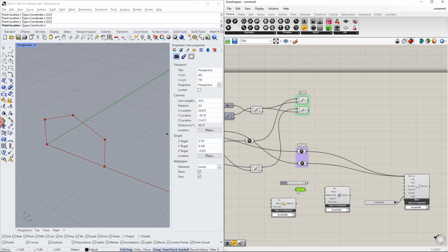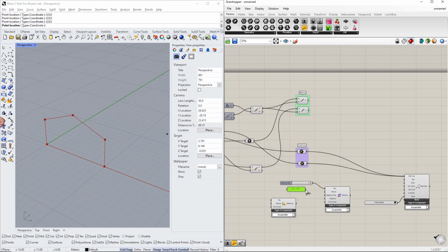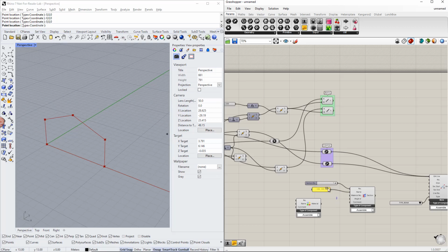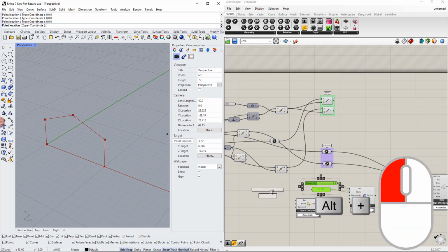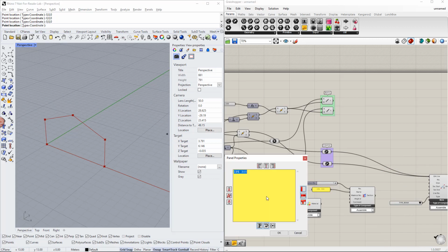Now we enter these properties. For the cross-section, we enter 1 as the section number and IPE 300 as the cross-section name. For the material, we enter 1 as the material number and S235 as the material name.